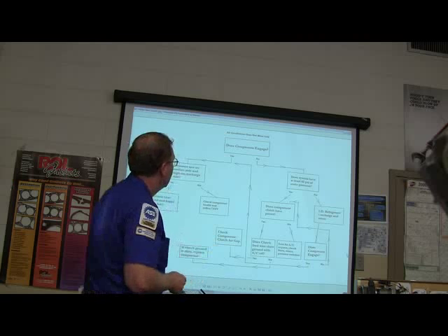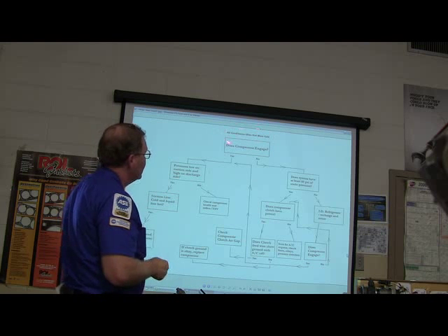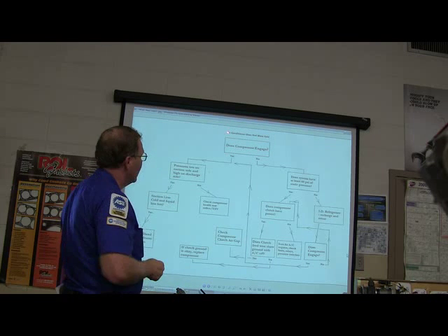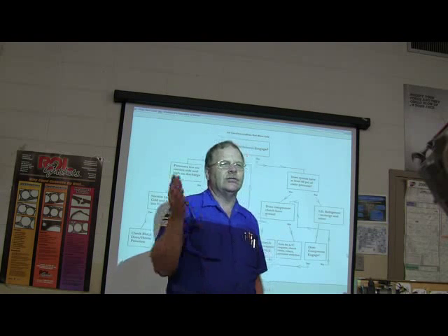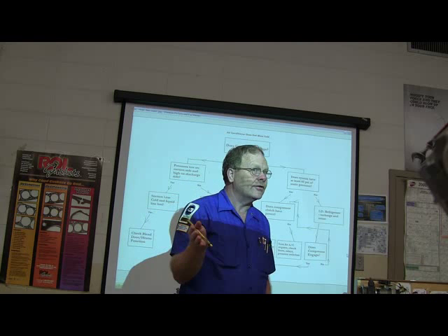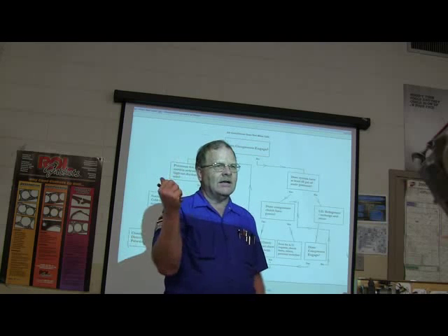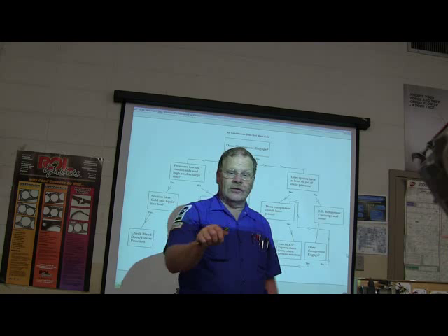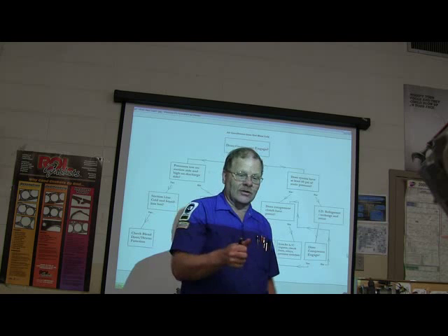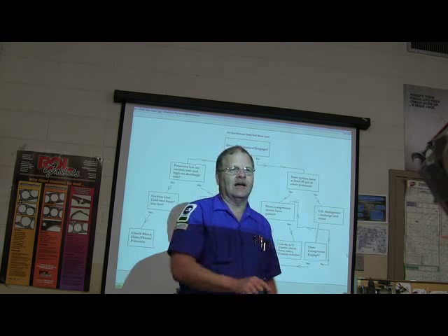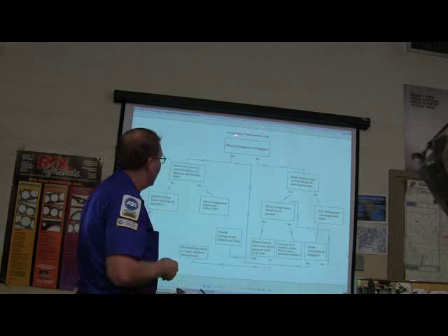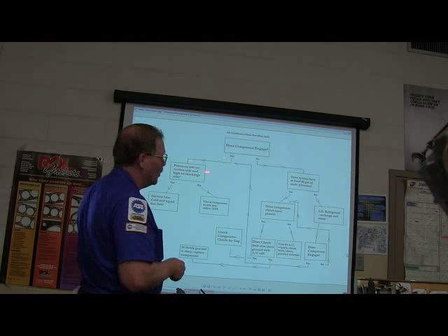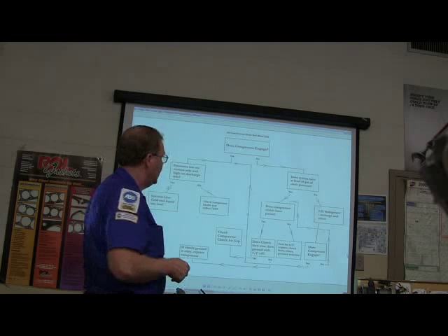You got me? Air conditioner does not blow cold. This is where you're going to start. Does the compressor engage? How do you know if the compressor is engaged? You turn on the air conditioner, make sure you know how to turn on the air conditioner. Because on that Black Ranger out there, you turn on the fan, but until you push the fan knob and a little orange light comes on, you haven't turned on the compressor. But make sure you know how. All right. Does the compressor engage? Yes or no? Got it?